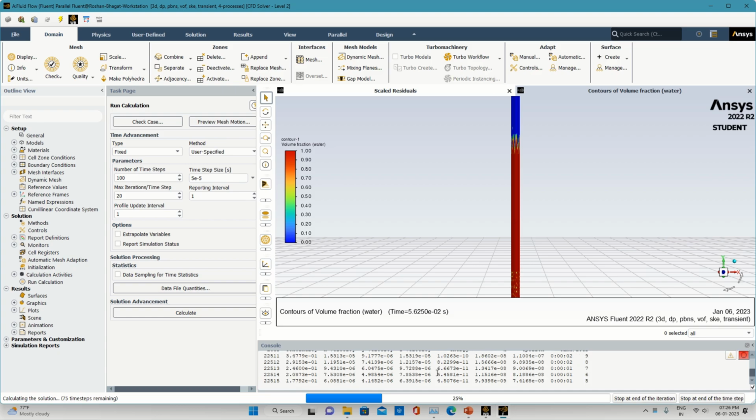So this is how to handle the floating point exception error. The error can be avoided by changing the mesh size with the help of the mesh option available. Take a different mesh size than earlier. If we take a mesh which is not too fine, the time required for performing the iterations will be less. So this is how it can be run. We'll check how long it takes. We'll complete these 100 time steps, and we'll see how the simulation plays out based on this.